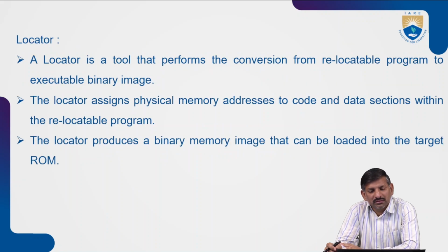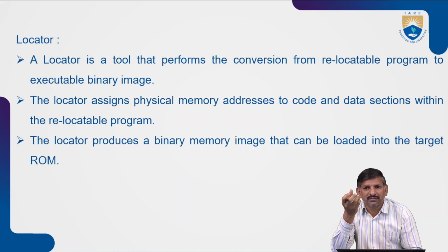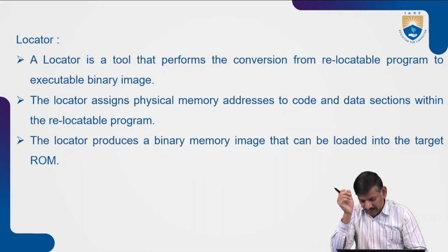A locator is a tool that performs the conversion from a relocatable program to an executable binary. The locator assigns physical memory addresses to the code and data sections within the relocatable program. The locator produces a binary memory image that can be loaded into the target read-only memory. That means it creates the executable image that needs to be loaded in the target hardware.